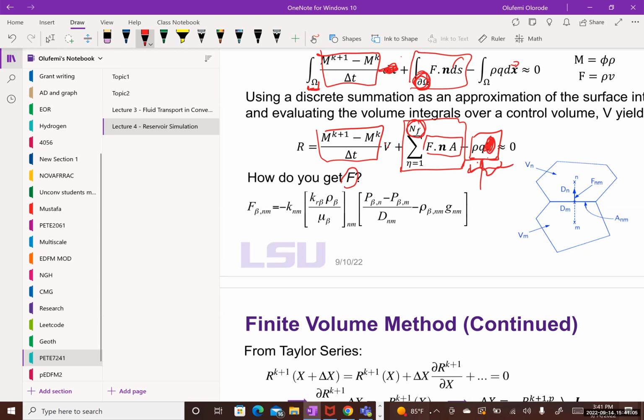So if the Q was written in kilogram per second or whatever, then you may not need to divide by volume. That's where the confusion comes from. So when you are writing your paper, you need to tell us what your unit for Q is. And then some people have used volume per time and they forgot that they need to divide by volume. So that's a common error.